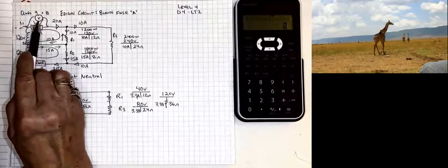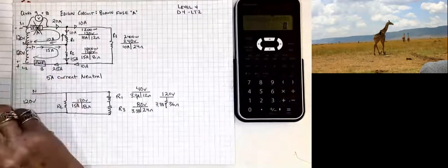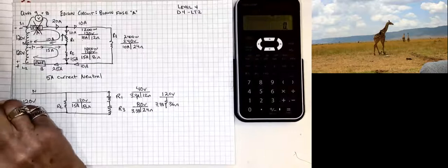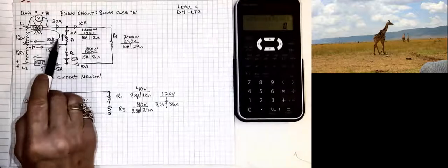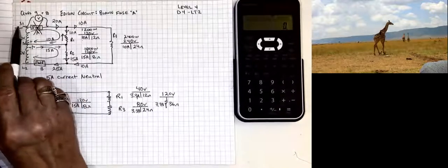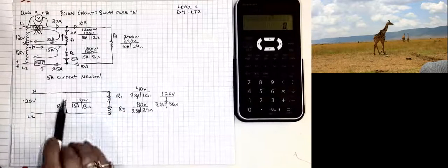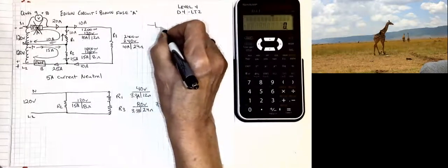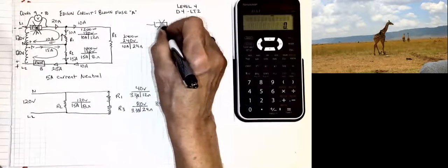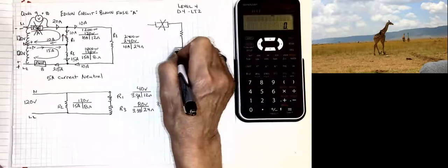Now the voltmeter has a huge amount of resistance. So there's really just a very minute amount of current flowing through the voltmeter to cause the meter movement to move. Usually it's in the range of like 50 microamps. Not going to actually drive the load, give us any voltage drop. And so what ends up happening is these voltages are all gone, and I now have these voltages. And so I'm going to put that over here. We have the fuse that is blowing. We come out to our neutral.